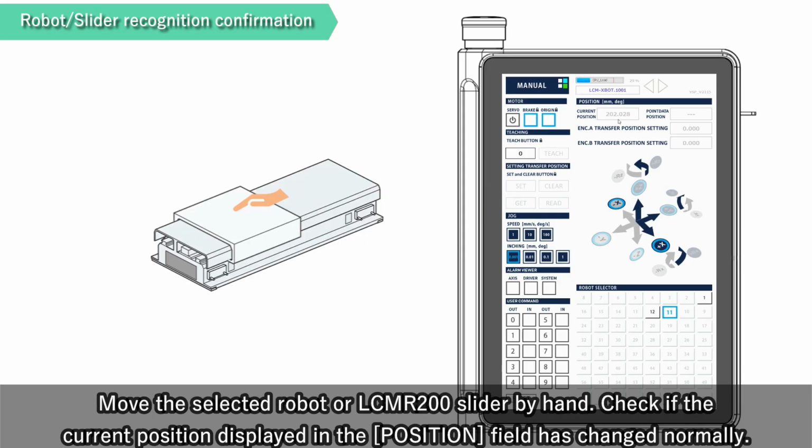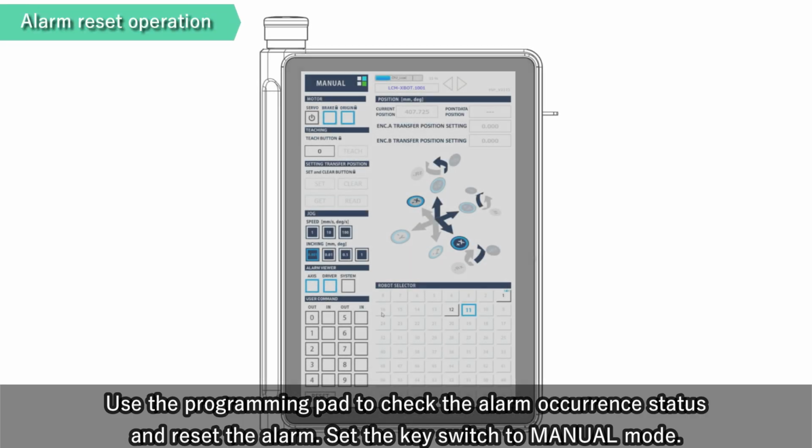Move the selected robot or LCMR200 slider by hand. Check if the current position displayed in the position field has changed normally. Use the programming pad to check the alarm occurrence status and reset the alarm. Set the key switch to manual mode.